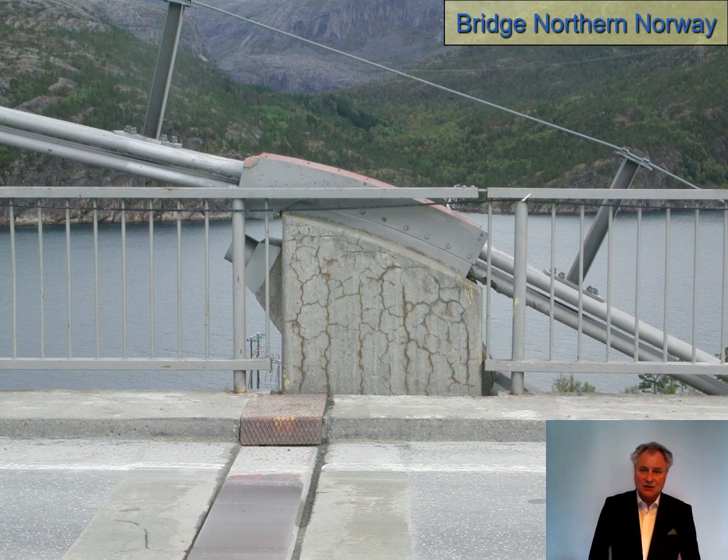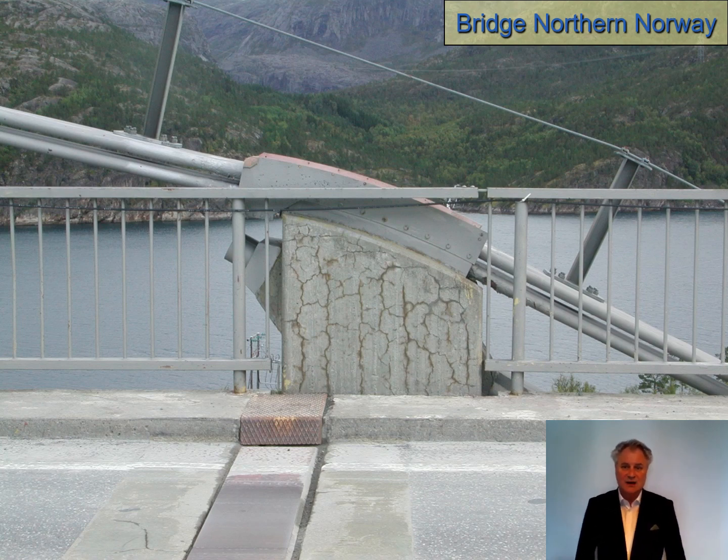Here we have a bridge in northern Norway, as you can see, close to sea, so there will be some sea water spraying over that concrete. And when you are starting to get some open cracks in map cracking in a very vital concrete element like this, you have a big problem. So it's a question because you have this map cracking opening and chlorides from the sea water are coming in and so on, and that makes quite a big challenge.